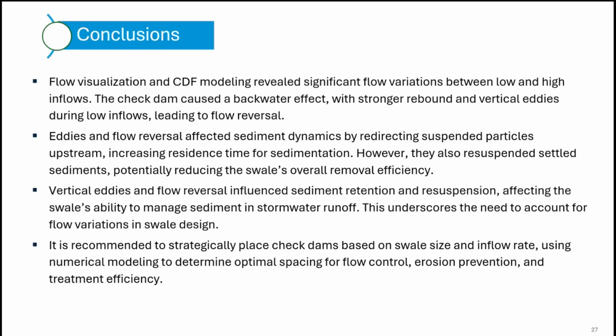We have to look at the dynamics of the flow, the location of the weirs, or if we need to have some sort of baffles to redirect the flow to make it more efficient. So we are recommending using modeling rather than just using a simple equation to design a bioswale.